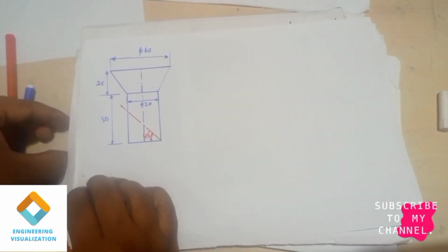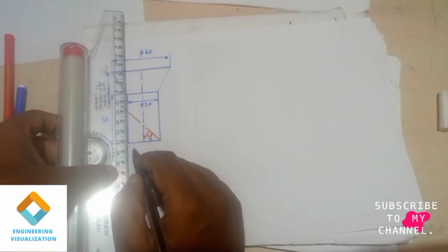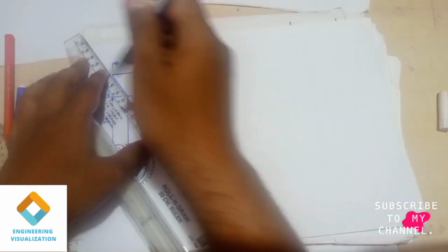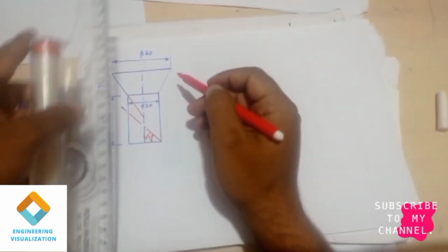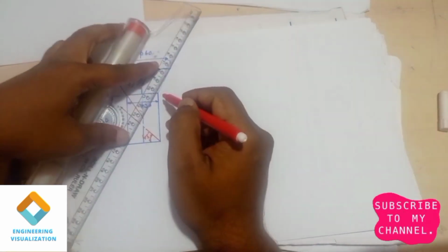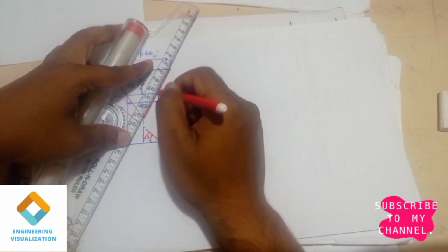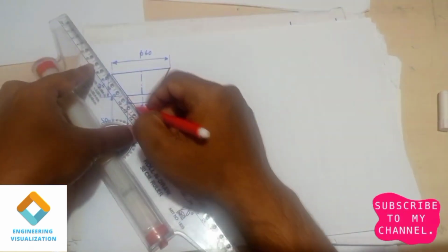Okay, now we need to construct the top view of this cylinder. In order to show the cutting, it will become very easy. So the upper part of the funnel, right? When we construct it, it will not be possible, so we will extend it to make it look like a cone. Construction of the cone, we know, uses the formula small r by capital R into 360 degrees. We can do that. So I'll just extend that. The tapered part will be easy for us when we do the development of it.